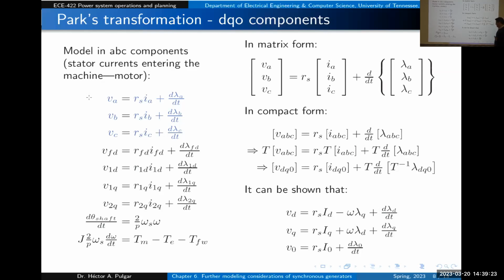And we formally defined this in 325 as a transforming voltage and a speed voltage. Because the reference frame is rotating at synchronous speed, it will have some dynamics and change. We see here the speed voltage due to the rotation of the rotor. That's the speed voltage we have in the DQ and 0 frame.